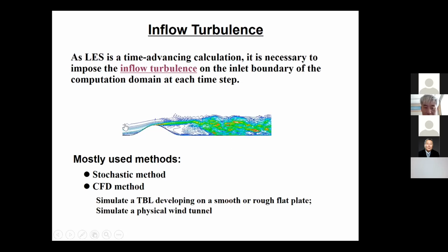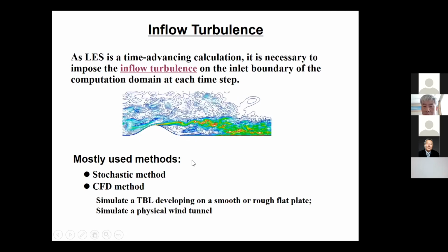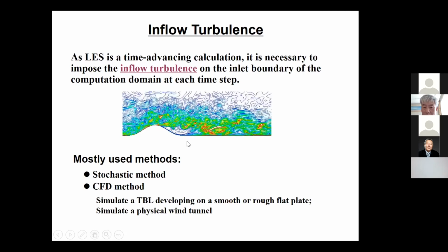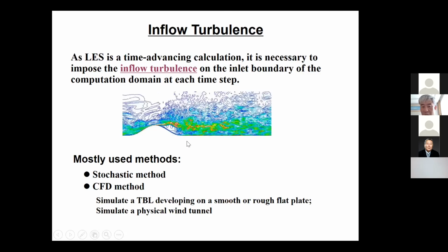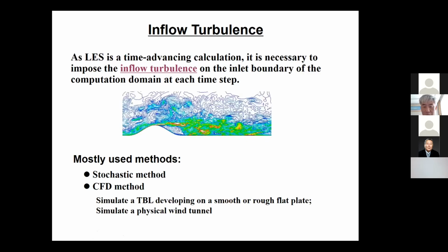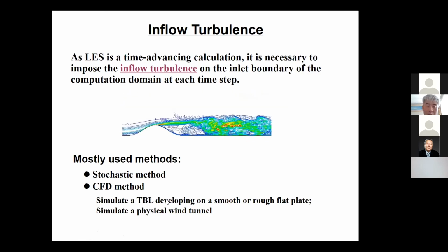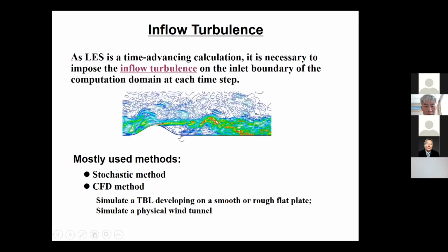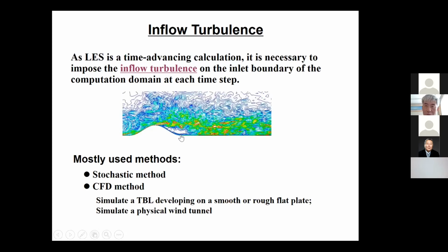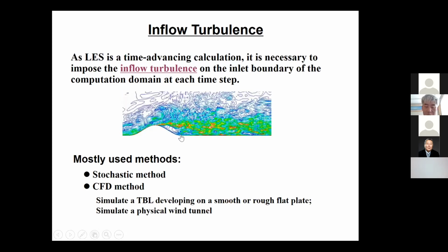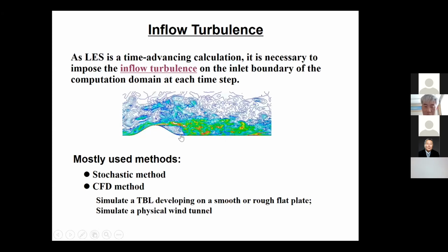So you can find that if turbulence comes, it will cut the separated shear layer and significantly change the flow velocity past here. You see a very narrow dead water region in turbulent conditions. So in a numerical wind tunnel, we also have to produce the turbulence.